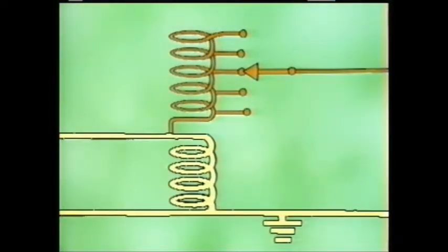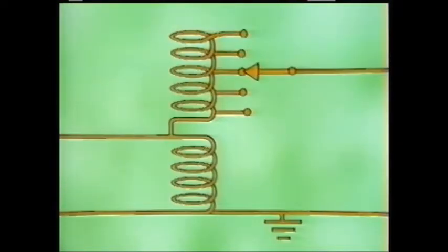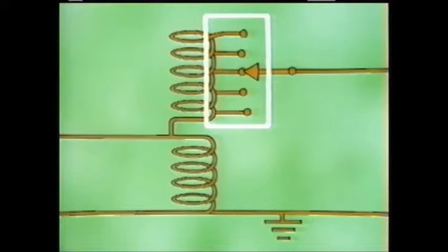When voltage is applied to the primary winding, the resulting current flow induces a voltage in the secondary winding. This is similar to the operation of the transformer we looked at earlier. However, unlike transformers, the series connection between the windings causes the primary winding to also function as part of the secondary winding. Depending on which tap connects the voltage regulator to the distribution system, the value of voltage leaving the regulator may be greater than, less than, or equal to the voltage applied to the primary winding.